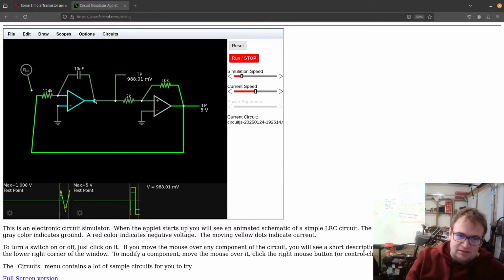So now this will start changing. It will go from 1 volt here. See, right now it's at almost 1 volt, and it's gonna go down to just over minus 1 volt when this is at minus 1 volt. That means that a half milliamp is gonna be flowing this way.